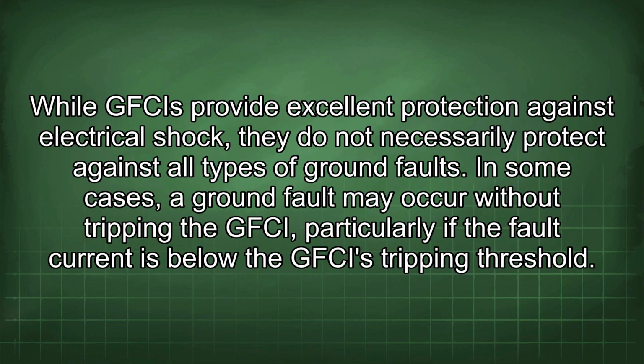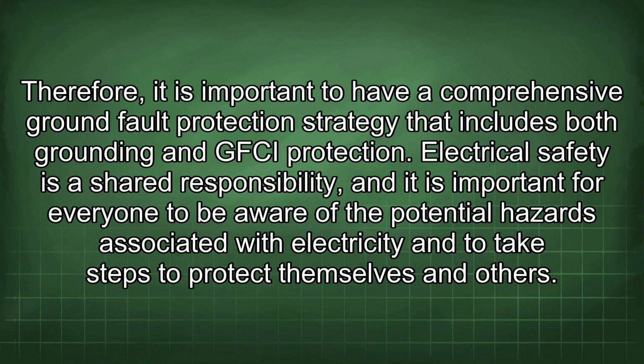While GFCIs provide excellent protection against electrical shock, they do not necessarily protect against all types of ground faults. In some cases, a ground fault may occur without tripping the GFCI, particularly if the fault current is below the GFCI's tripping threshold. Therefore, it is important to have a comprehensive ground fault protection strategy that includes both grounding and GFCI protection.